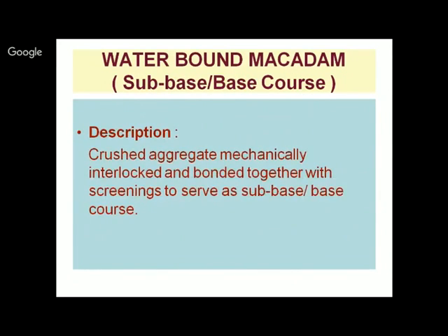This is mechanically interlocked and bonded together with the screenings to serve as a base or sub-base course. Now when we say sub-base or base course, this implies that in some types of very high quality roads, WBM or water-bound macadam at its best can work as a sub-base, but in case of slightly less important roads, it can work as an even base course also.